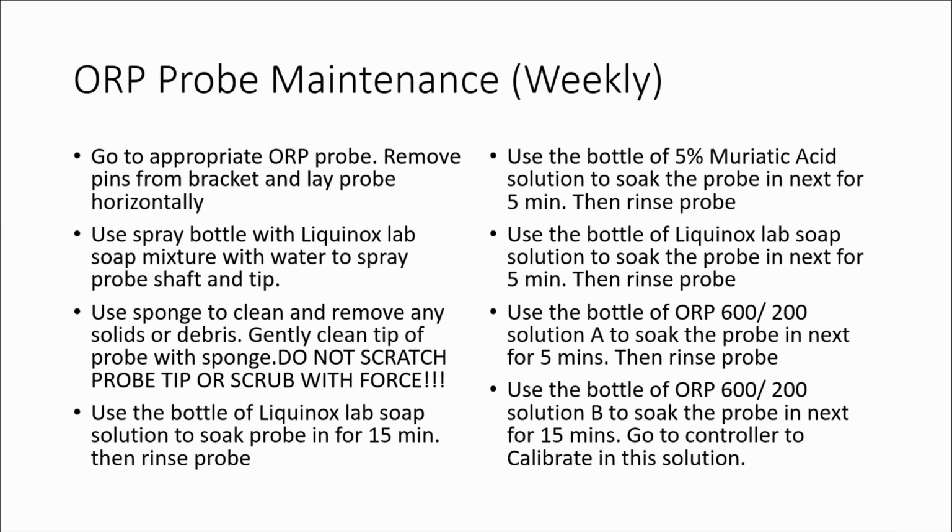The other thing is we learned the hard way. These probes are about $2,400. It's a single point calibration. So you do not go from 600 to 200 solution one right after another, because that will poison the probe and actually cause the probe to go bad. We learned that the hard way. That cost us, I think, two probes when we realized what had happened. So you're following the manufacturer's requirements on that. Which we have changed for them.